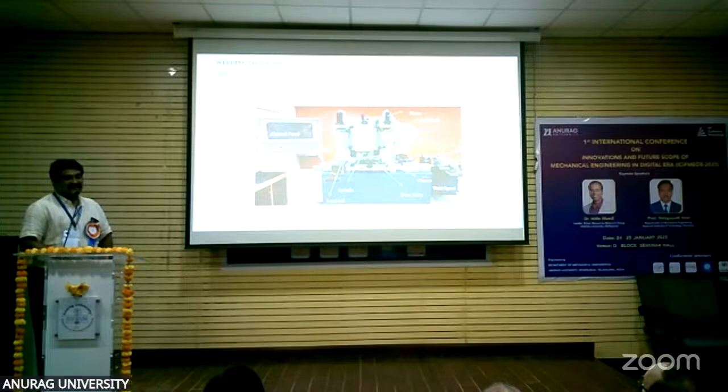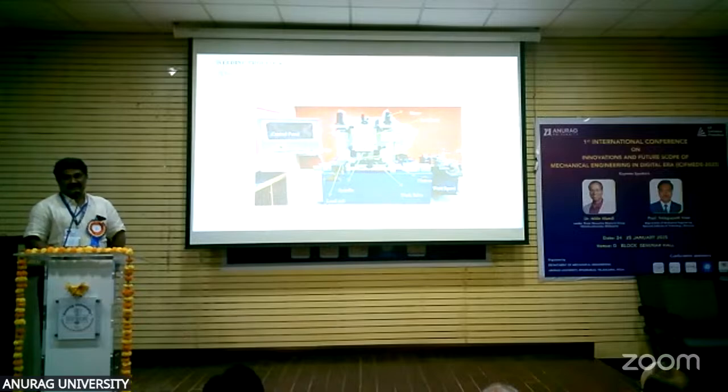The next combination is 1350 speed with 16, 26, and 36 weld speed. Like this we followed for 1800 also. That way we did a full factorial of 9 experiments, and we compared with the base material to see what impact the tool profile has on this weld.